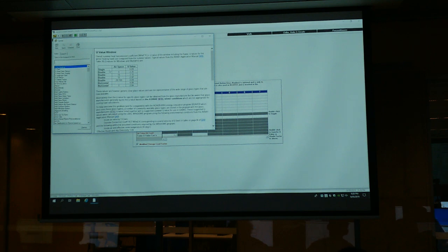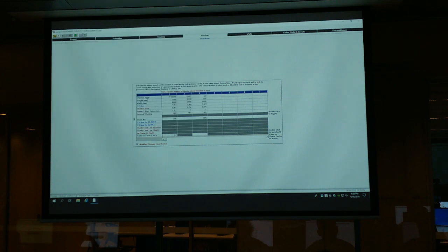And then you got single glass, double glass, and the air space between the two glasses, and what's the U value given. Okay? I think the project instruction sheets shouldn't have any confusion. I just copied one of them, should be easy for you to find. And the shape factor, and then with blinds or whatever. Basically what we need to do is this part, not this part.